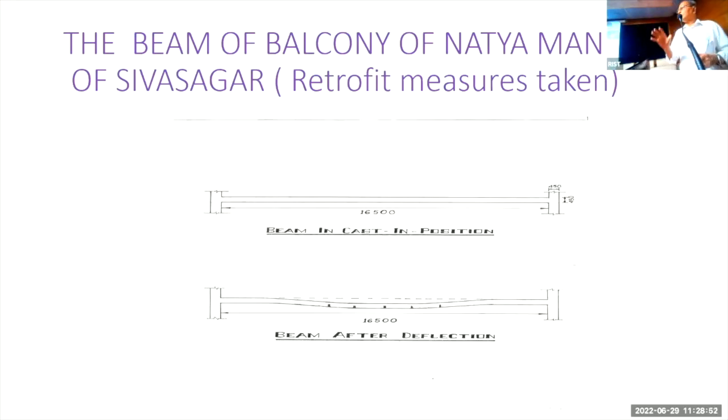On that basic concept, I designed the retrofit measures, and to do that, what I did, I drew 2 cantilevers from the back. I will not go for the details, and gave 2 supports in the middle without posts. The support was provided by cantilevers drawn from the back. So this shows the lack of basic knowledge on the part of the designer.